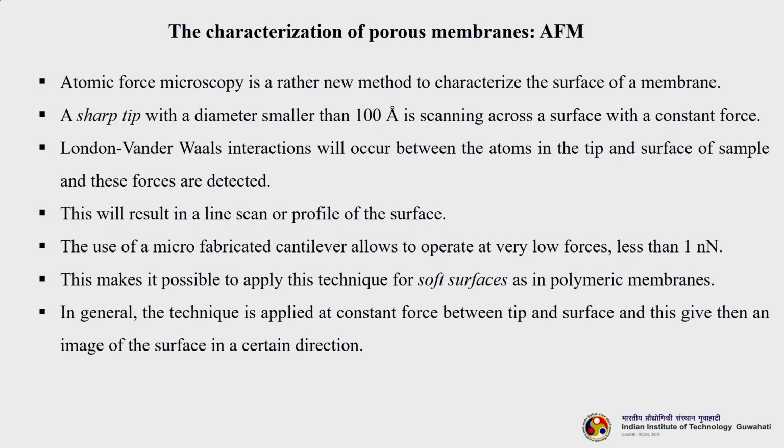Here London van der Waals interaction will occur between the atoms in the tip and the surface of the sample, and those forces are detected. They will eventually result in the micrographs. So, this will result in a line scan profile. The use of a microfabricated cantilever allows operation at very low forces, less than 1 nanonewton. This makes it possible to apply this technique to soft surfaces, as in polymeric membranes. In general, this technique is applied at constant force between tip and surface, and this then gives an image of the surface in a certain direction.